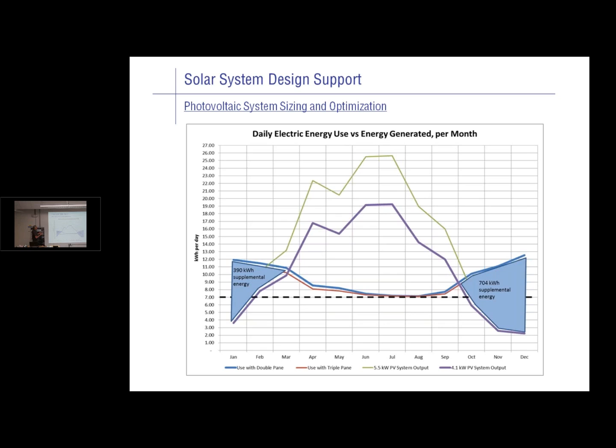So the first thing we're doing, and it's an all-electric modular house, but we have to have a thermal model because the heating energy end use is the most significant end use, even though it's a heat pump. And so the thermal model translates to an electric load model, and you can see the two lines here. These are our average kilowatt hours per day over the course of a month. So inside the hourly reports, I've massaged this significantly to get it down to something where the architect and the owner can actually look at this graph and go, okay, I get it.